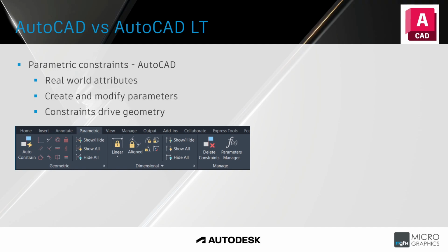And if it is a polyline, both lines will move, but the geometry changes, the length changes, it stretches, the angle changes as well. What constraints allow us to do is lock in real world attributes, or real world things that will help us define something. So take a rectangle, for instance. If I've got a rectangle and I draw it maybe with the rectangle command in AutoCAD, if I grab any of those corners and I pull, that 90-degree changes and it's not a rectangle anymore.